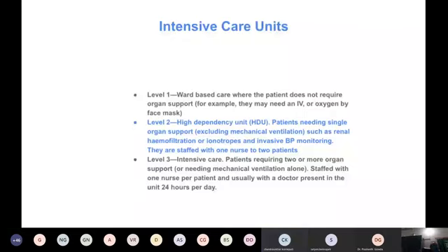Level 2 has to be ISO 7, which is class 10,000 as per US 209E. And level 3 is intensive, and this has to be between class 1000 and 10,000 in terms of filtration. In terms of temperature and relative humidity parameters, temperature should not exceed 24 to 25, and the RH level has to be maintained below 55 to 60%.